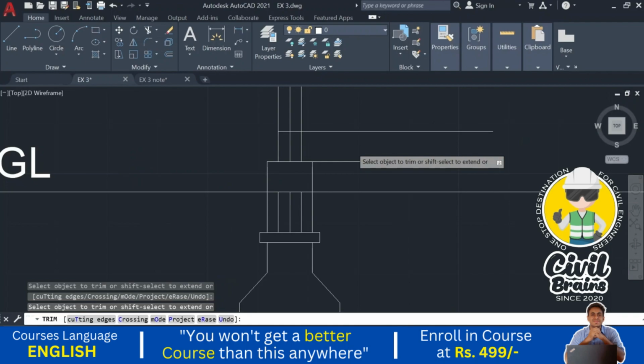After the steel mesh, whatever the dimensions or size of rebars are given according to the structure, that we need to provide. Above the mesh we need to place the column. So column reinforcement we need to place above the mesh of the footing. After the column reinforcement we need to do the shuttering work, and after the shuttering work we need to place the concrete, or pour the concrete. Okay.